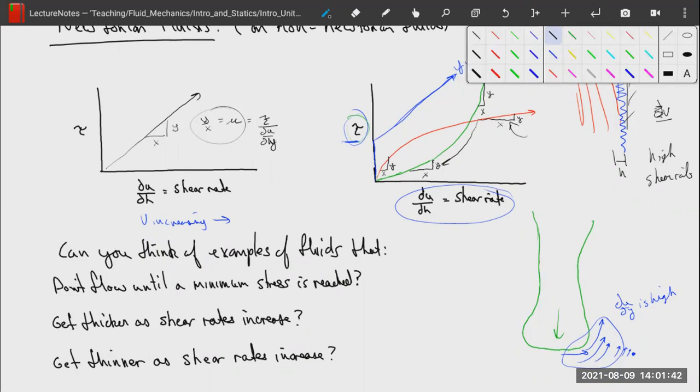And then as soon as something hits it that has a lot of kinetic energy and is moving fast, like a bat or a bullet or something like that, the amount of shear greatly increases because the velocity greatly increases, right? A bat hitting you is going to move much faster than you twisting around or moving your arm, right? And that increase in shear rate will cause it to stiffen up and absorb a lot of that energy and hopefully protect you.